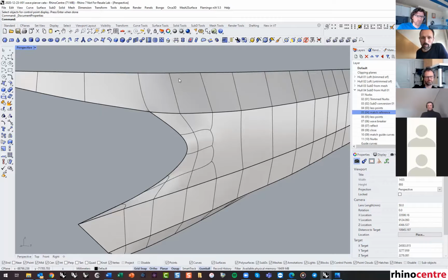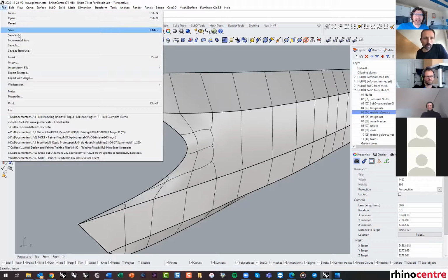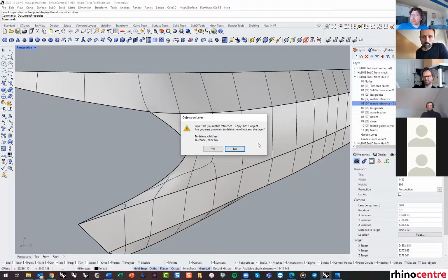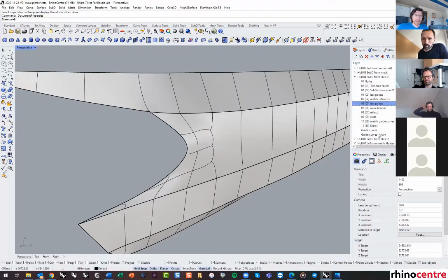But then you would actually, Gustav, you would have to do an auto incremental save. Otherwise, you don't have all these versions, because the autosave will just override every change you've been making. Yeah, you can also do incremental save in Rhino here, but I like to keep it in my file. So I do manually every now and then, right mouse click, duplicate layer and objects, and I rename it, and then I continue working. So this way I can trace back my whole process.